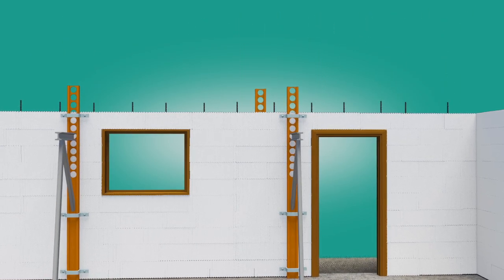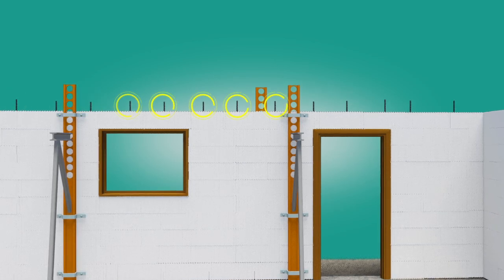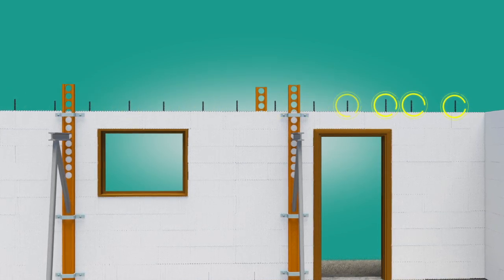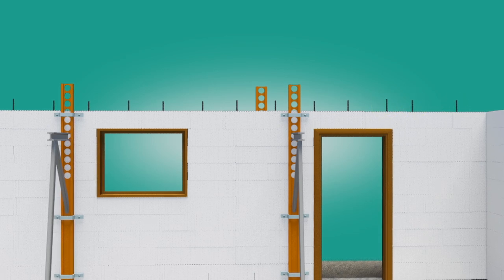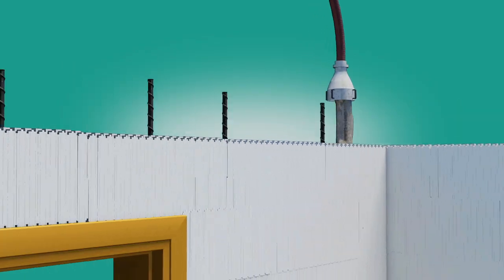Stack the block to the full wall height for single-story construction, or just above floor height for multi-story construction. Begin installing it from the opening at the top of the wall through the spaces between the horizontal rebar.